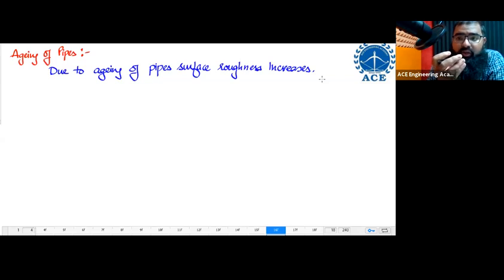Water sometimes comes out rusty from very old pipes. Because pipes are older, corrosion takes place very fast, especially near the sea. If you open the tap, rusty water comes, and only a very small quantity comes out. Over a period of time, the discharge capacity becomes lesser.